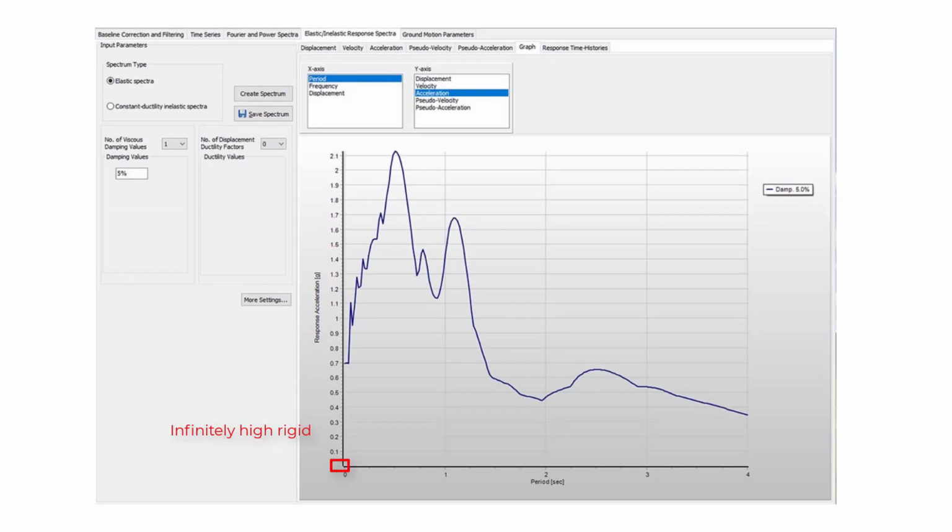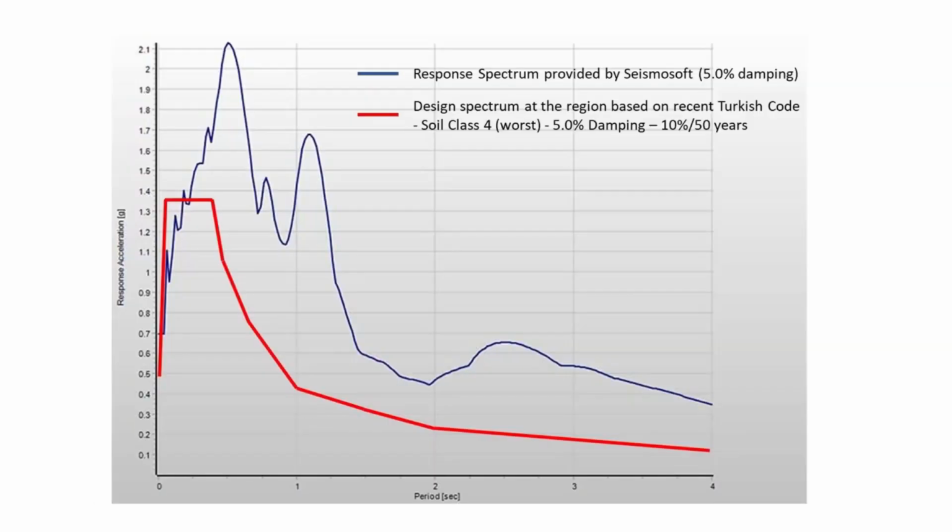So we have overlaid the spectral acceleration graph of this station with the codal design response spectrum graph for this zone. You can see here, both are put together. This indicates that the spectral acceleration for this earthquake at this station exceeds the design response spectrum. Yes, the codal design response spectrum is constructed based on the design basis earthquake, that is the DBE. That means the MCE level is further brought down to the DBE level by some factor. But still, the spectral acceleration curve is high and seems to exceed the target level for this situation.